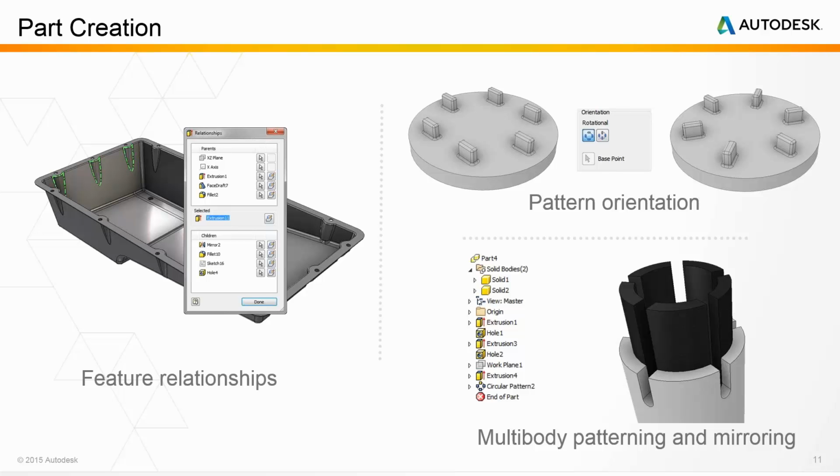So in this case, where we've got a circular pattern of a feature, it may be a slot or may have to be aligned with a slot, giving movement in a certain direction, you can actually lock the orientation of those features rather than having them rotate around the axis of revolution.